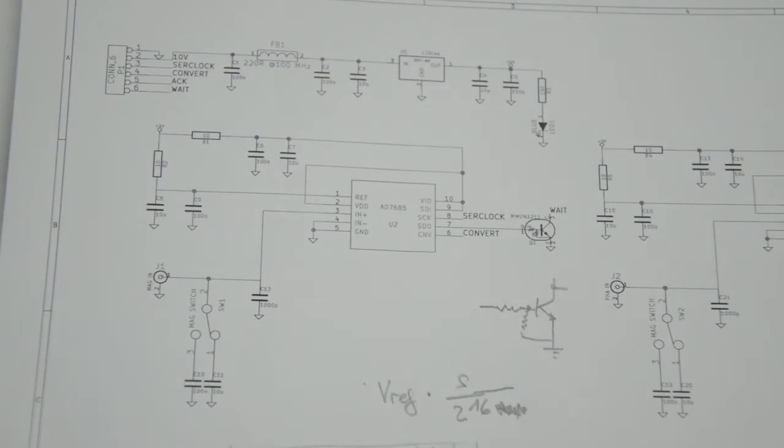The ADC used is an AD7685, which is a 16-bit charge redistribution ADC. And that last part really relates to how it works. Internally, there is a bunch of capacitors that are actually switched in a pretty clever way to eventually shift out the measurement. And if anyone is curious, I'll link a description of how that works.